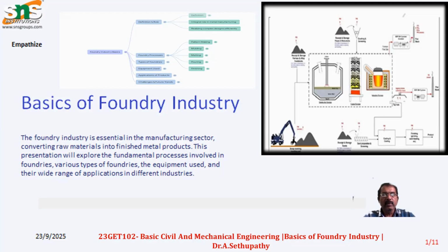Before we discuss this foundry process, what is a mold or molding? A mold is sand rammed in boxes, with the impression of the part shape that we need. How do we get the impression in the sand? First, we make a pattern.